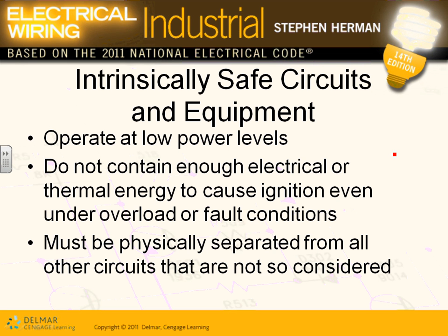Now, don't think you're going to use an intrinsically safe system to power a 50 horsepower motor in a hazardous location. It's not meant for this, guys. Intrinsically safe systems are meant for class 1, class 2 and class 3 location control circuits. They use these as control circuits for the equipment, or signaling circuits, sensors, and so forth. They are all low voltage. Can I get you guys to understand these are low voltage circuits, class 2 and class 3 circuits and signaling circuits. What they do is drain them out of power.